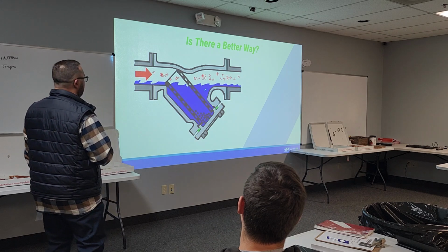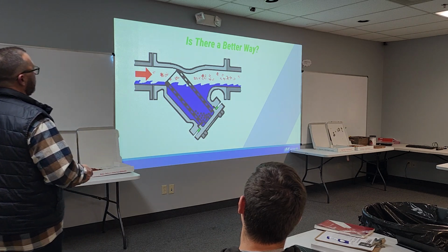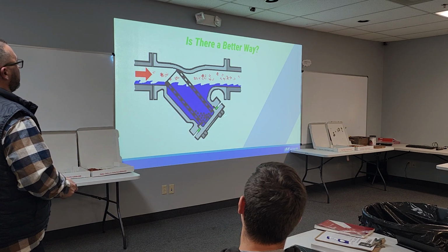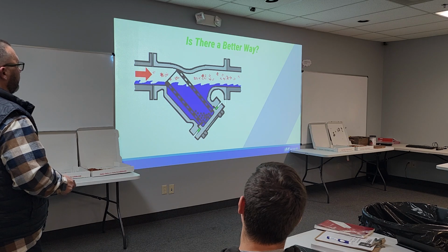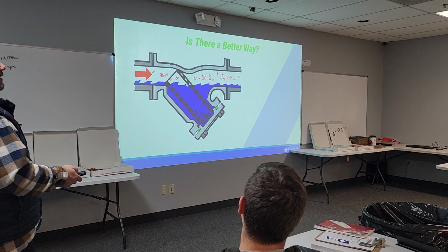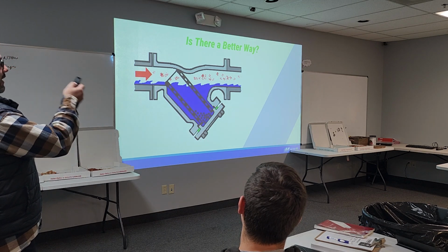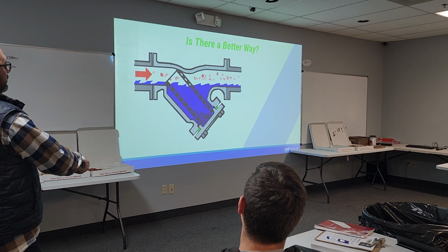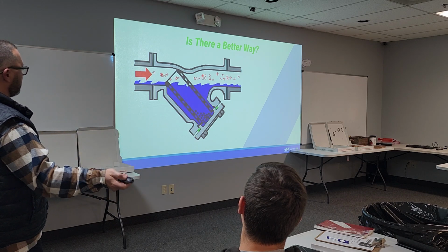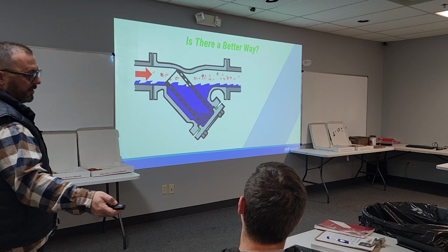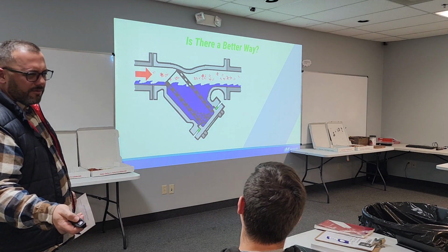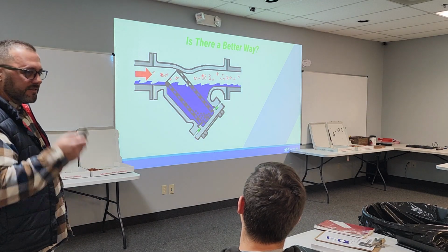This is what we talked about with the strainer. Again, on a 20 to 40 mesh strainer before a steam trap, good piping practice dictates every steam trap has a strainer right before it, has a check valve right after it, so you don't backfeed steam in. We can talk about, okay, is that a horizontal line or vertical line? We can get in the weeds and talk about that.